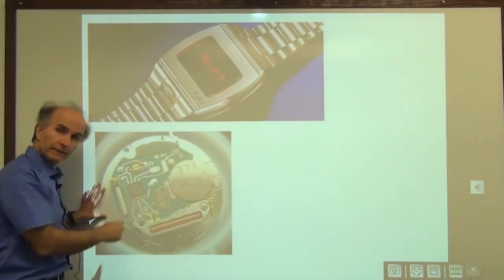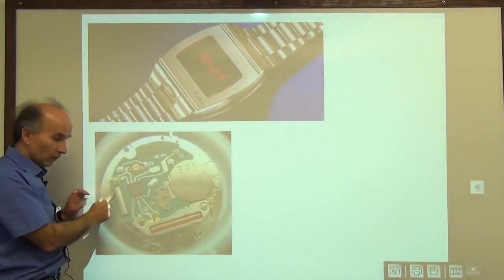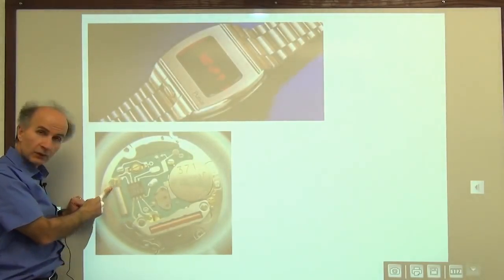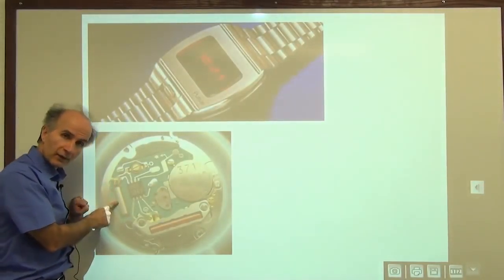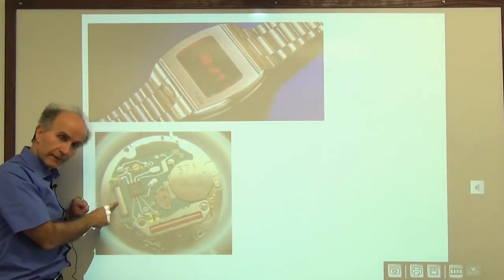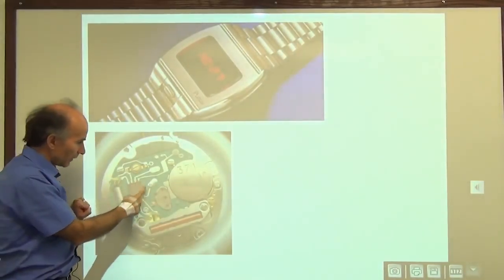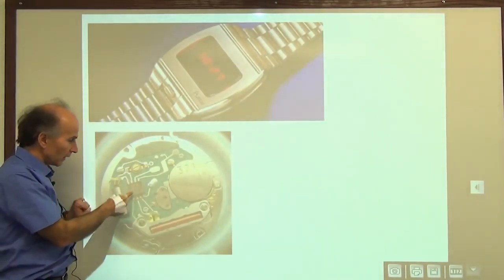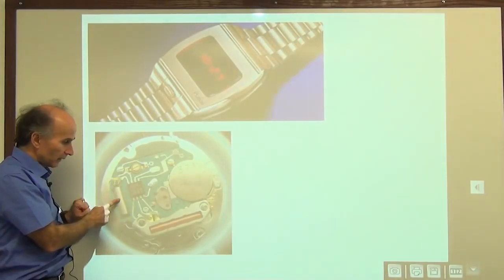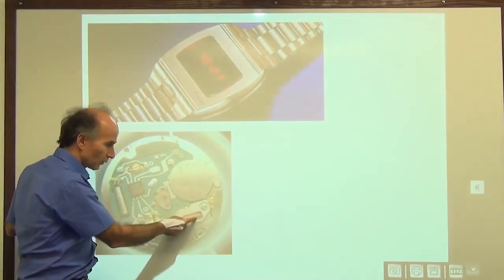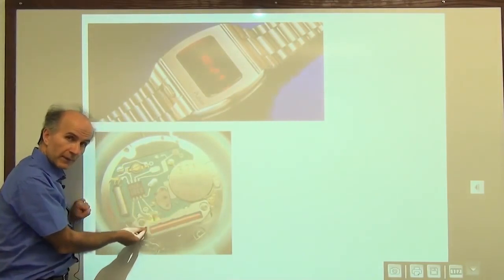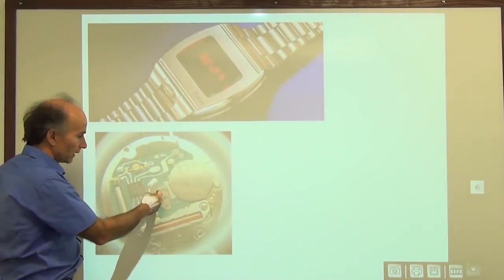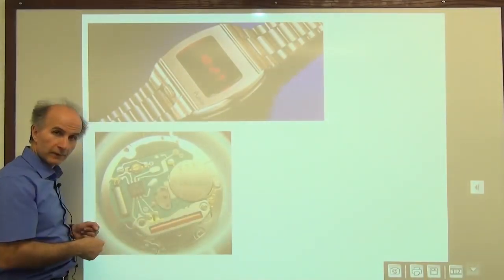We have a watch battery. Then we have what we call a crystal. You see this little cylinder here with 2 legs, 2 terminals. This is a quartz crystal. It's a crystal made of quartz. And then we have a little IC here. There's some circuitry inside this chip. And then the result of this guy and this crystal drives a coil. You see this is a coil. It's a wire wound around something, around the core. And this gives certain pulses to the gears inside the watch.